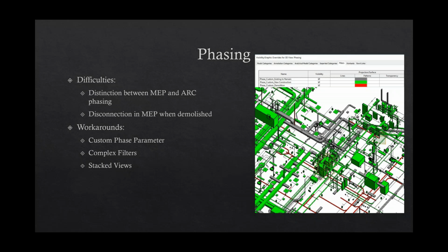The other nice thing with this is if I have complicated phasing. I had a project that had 8 different phases at one point, and I needed to control documents showing some combination of, say, things in phase A happening at the same time as phase C, but not the same time as B. That would be impossible with Revit phases because they're purely linear. Once you go past a phase, you can't decipher what's back, since it only has a view of previous, not a view of selected aspects of previous.